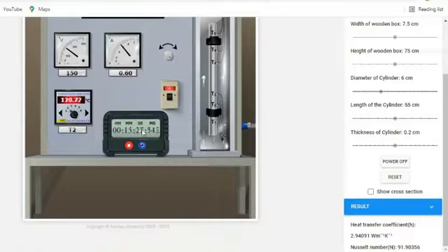So up to 20 minutes you just watch it, and then it gets steady. Now here you can see 30, 148, 150, 154, 156, 36. Everything is as it is. The temperatures don't change. But look at the impact on the Nusselt number. It increases. Now by decreasing the diameter, the Nusselt number increases.